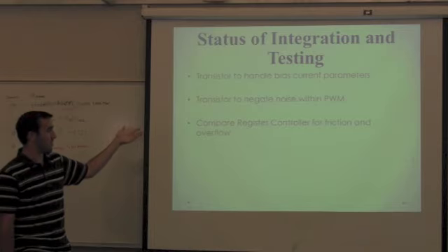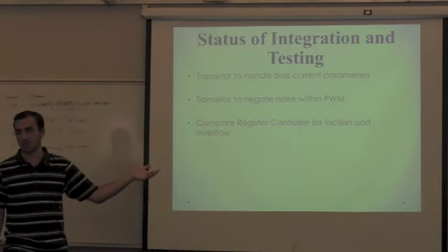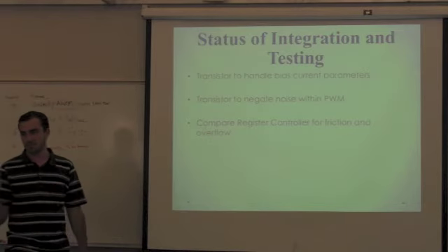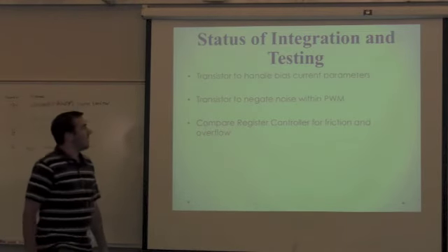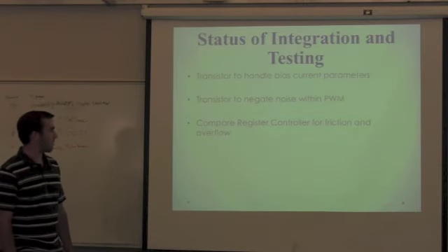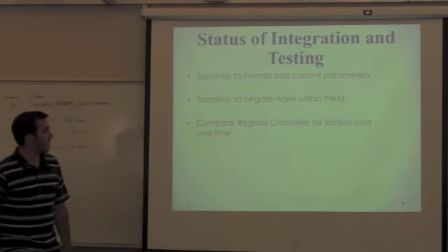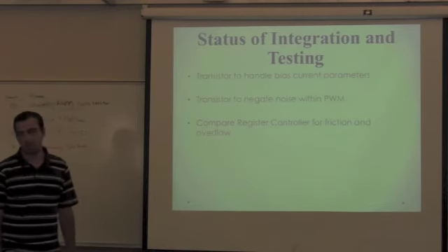Initially, we were going to use MOSFETs, but the capacitive loading values caused too much noise for the fan to really have the accuracy of the duty cycle ranges that we wanted.